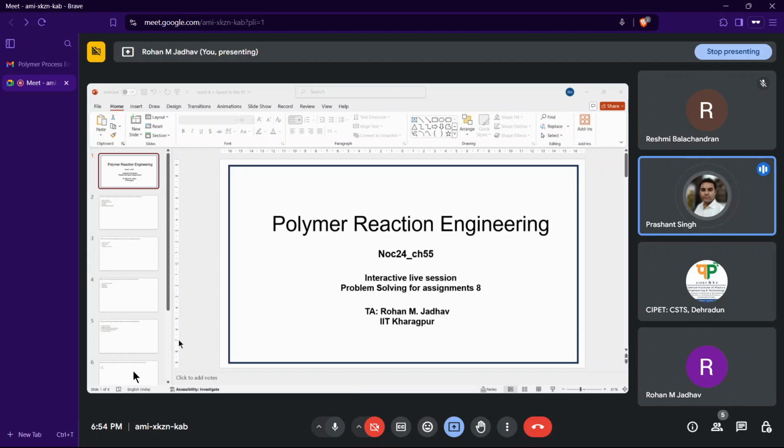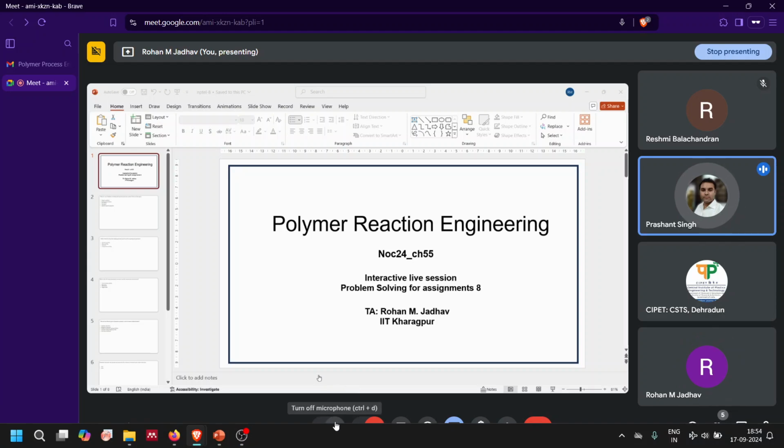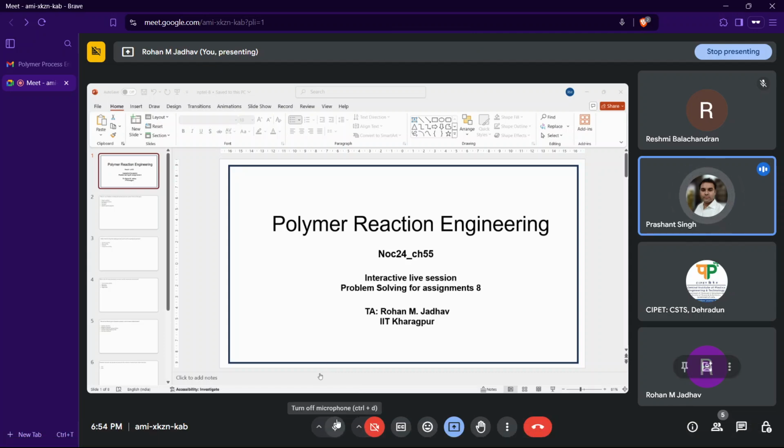For delamination, I thought that whenever we inject a material in a mold and allow it to cool, the part that is just in touch with the mold will get cooled rapidly rather than the internal part or the center. So due to uneven rate of cooling, there may be a chance of forming a layer that will create delamination. Yes, that is the case. Correct, because we know that polymers are thermal insulators, so the cooling is non-uniform. But that same condition will be associated with moisture only, because in a simple material, if everything is okay, delamination normally is not taking place.